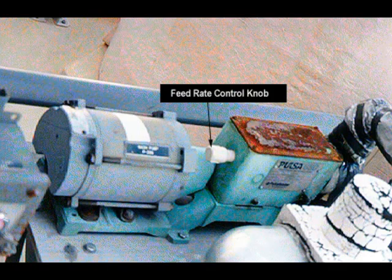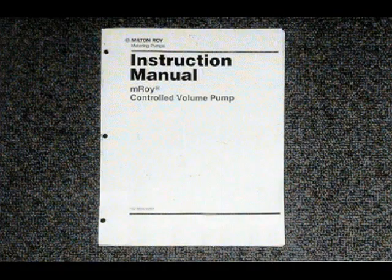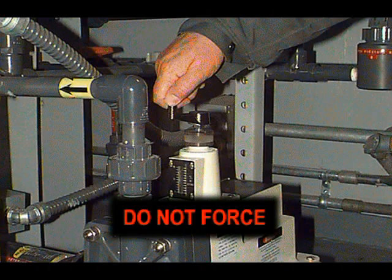Most equipment manufacturers give graphs or tables that give the feed rate for each setting of the control knob. Calibrate the pump yourself by measuring the volume delivered in a certain period of time at various control knob settings. When making adjustments to the feed rate, be sure to follow the manufacturer's instructions. If a knob is involved, never use force to move this knob. The pump will be damaged if you do. A sign placed near the pump will serve as a reminder of this point.